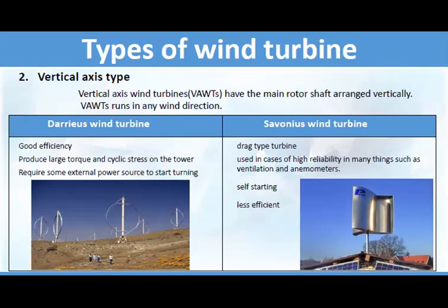It is also an advantage when the turbine is integrated into a building because it is inherently less steerable. Also the generator and gearbox can be placed near the ground itself, using a direct drive from the rotor assembly to the ground-based gearbox, improving accessibility for maintenance. However, these designs produce much less energy averaged over time, which is a major drawback.